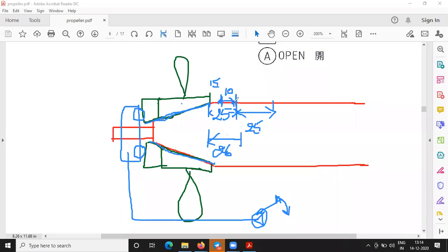So how will you come to know that it has moved 26 mm? Because once this point is covered under this, you'll not come to know how much it has been extended from this point. That's why we are taking another mark at a further 25 mm, so that after the first 25 mm is completely covered, we can calculate the distance which is left after here. That is the reason why we mark 25 mm first and then another 25 mm. Understood? Yes sir. And the dial gauge is mounted at this point. Now, as and when this is there, I'll slightly give some pressure.